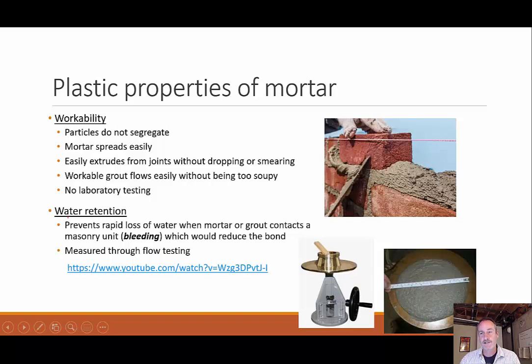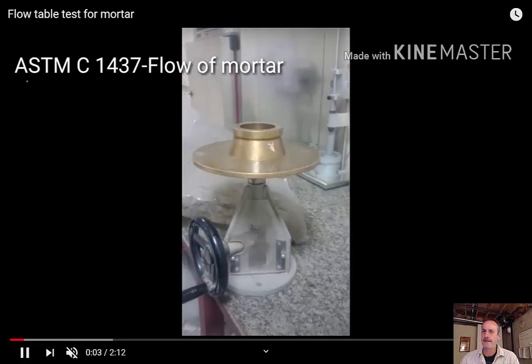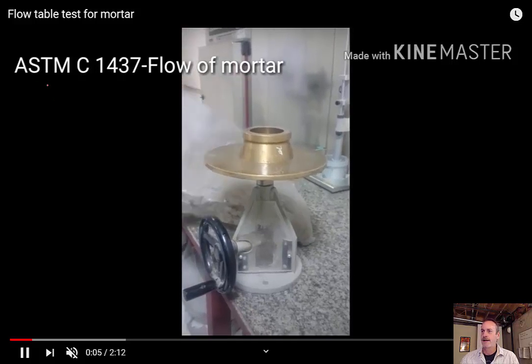Now, for water retention, like I said, the masonry units can suck out that water. It's called bleeding. And that can reduce that bond, like I said earlier. Now, there is a test for this. It's through this idea of flow testing. And once again, we'll see if we can get the YouTube to work. So, and this will walk you through the whole thing. This is an ASTM test.